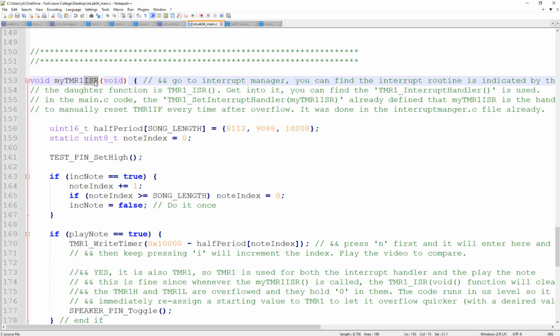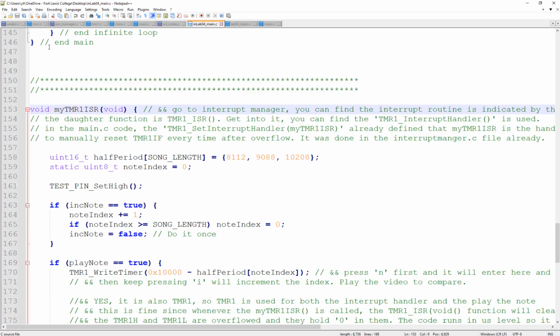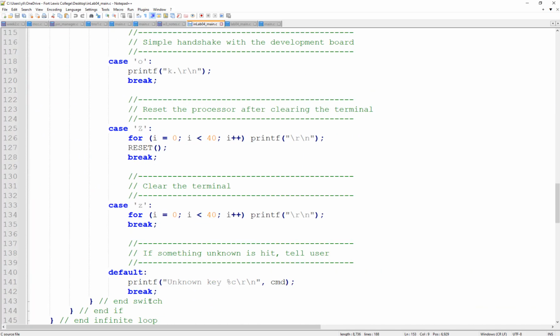So now the interrupt routine is a function. Whenever the timer is up, it's going to jump directly into this function and do whatever it does. So this will be independent of everything, every program in the main function. Think about it. It's just a new concept we have ever learned, all right? What's happening is you have your main loop, right? Let me just show you on the paper.